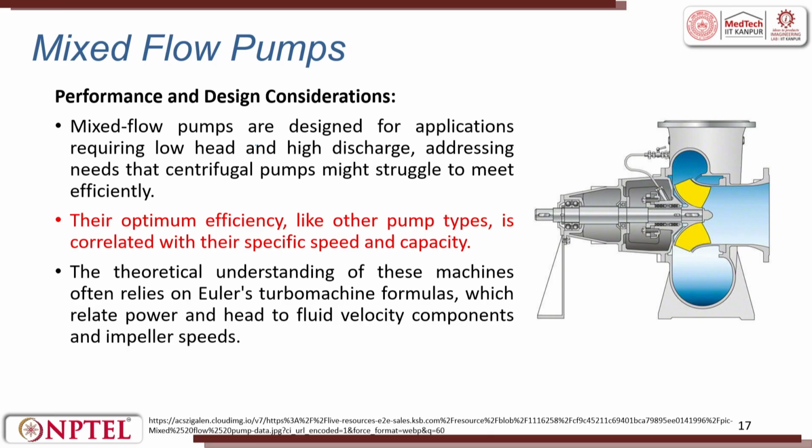Mixed flow pumps are designed for applications that require low head and high discharge, addressing the need that a centrifugal pump might struggle to demonstrate. So, wherever the centrifugal pump fails, we always look for a mixed flow pump. Their optimum efficiency, like other pump types, is correlated, and their specific speeds and capacity are high. The theoretical understanding of these machines often relies on Euler's turbo machinery formula, which relates power, head, fluid velocity component and impeller speed.